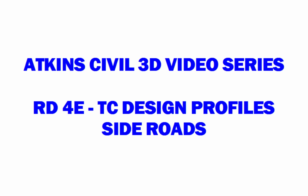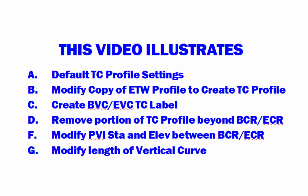Atkins Civil 3D video series, Road 4E, top of curb design profiles, side roads. This video illustrates: A. Default top of curb profile settings. B. Modify a copy of the ETW profile to create the TC profile. C. Create BVC and EVC top of curb labels. D. Remove the portion of the TC profile beyond the BCR and ECR. F. Modify the PVI station and elevation between the BCR and ECR. And G. Modify the length of the vertical curve.